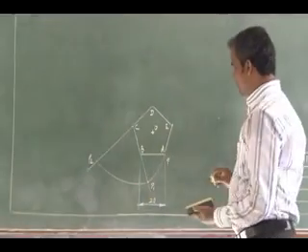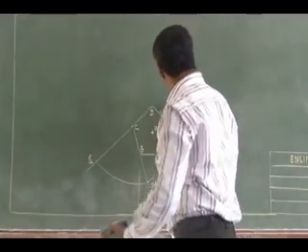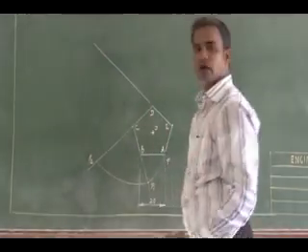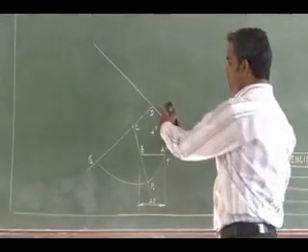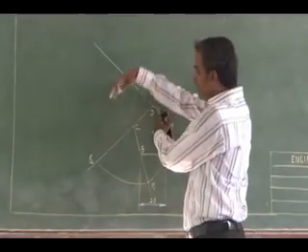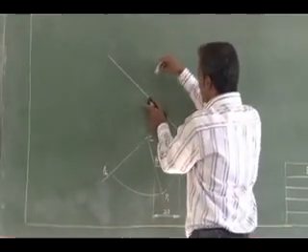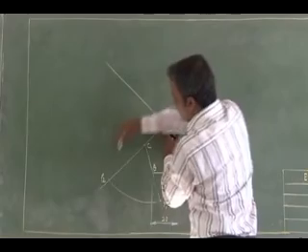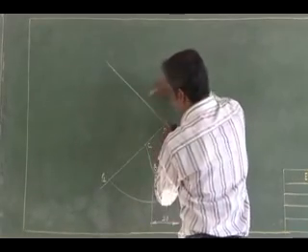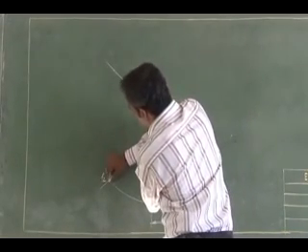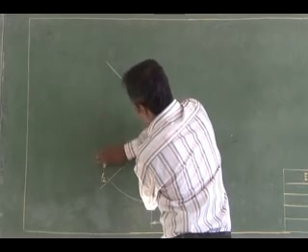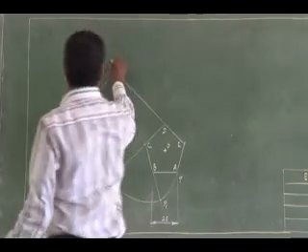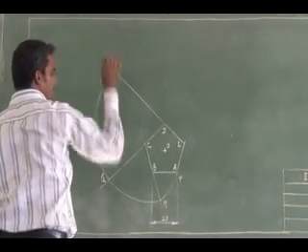Then extend ED in the negative direction. Keeping D as center again, DP2 as radius, that is nothing but 60 mm radius. I can extend the same radius, so I will end up at the involute point P3.